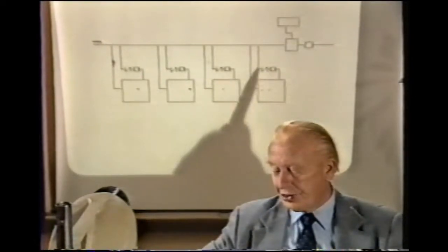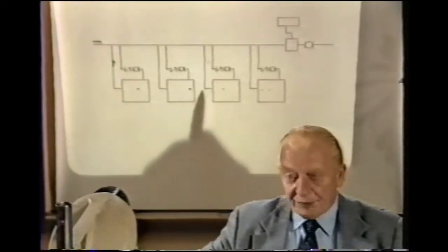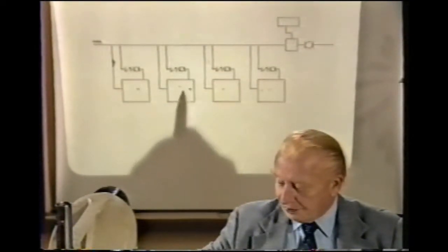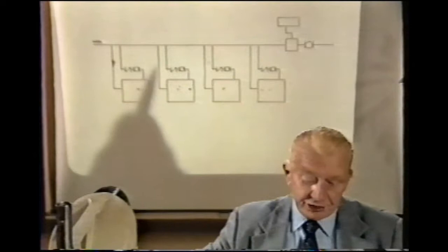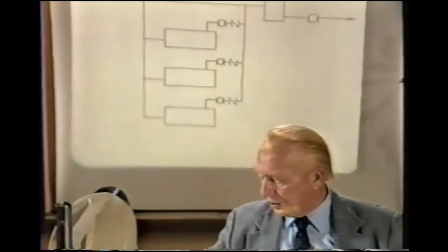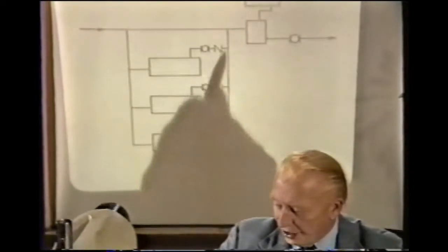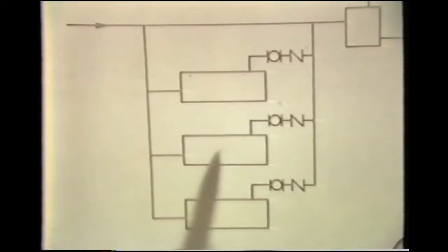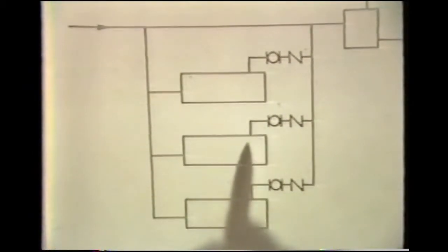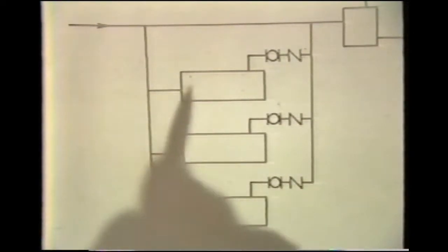This illustrates the boilers in series with a startup such that if temperature is not maintained, a second boiler is started. If temperature is not maintained through the second boiler, a third boiler, and so on and so forth. We can also apply boilers in equipment rooms so that we apply the supply and return measures directed to boiler application 4 in a manner similar to application 4, the chilled water application.